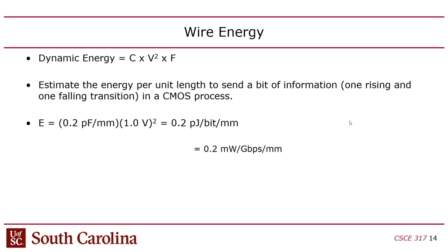That doesn't mean that every wire is going to be switching at that frequency. I mean, sometimes chips just sit idle, right? It's true, but they usually use the F as a generic idea of at what rate you expect bits to flip. That's F. So flips per second. And then capacitance is the capacitance. That's also part of the energy equation. So hopefully you guys are familiar with this equation from 212. That should have been covered in 212.